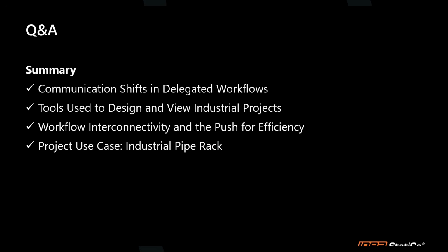So in that case, for the web, probably it was at the elastic limit. It was red, but it wasn't failing. It was only the stress on that plate. And we allow that material to go into the plastic area a little bit, and that's why it wasn't highlighting as failing, but it was in a high utilization ratio for that. So that's that.